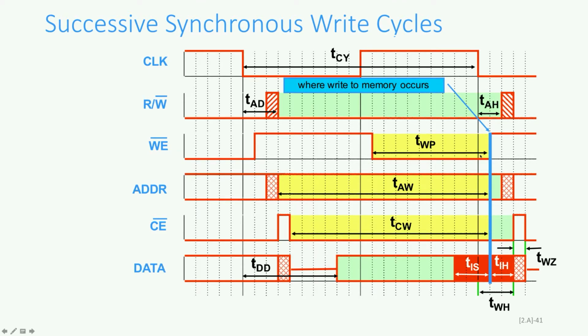And so again, just like in the previous diagram, these are the maximum values that an SRAM can have and still satisfy the timing required. So if the SRAM has a write pulse width that is half of this size, then that's no problem, because the write pulse is held valid for at least that much time. If the write pulse width is longer, then that's bad, because you're not actually holding it long enough. Same with TAW, this is the maximum amount of time that takes. Same with TCW. This is the maximum amount of time that you can possibly have.